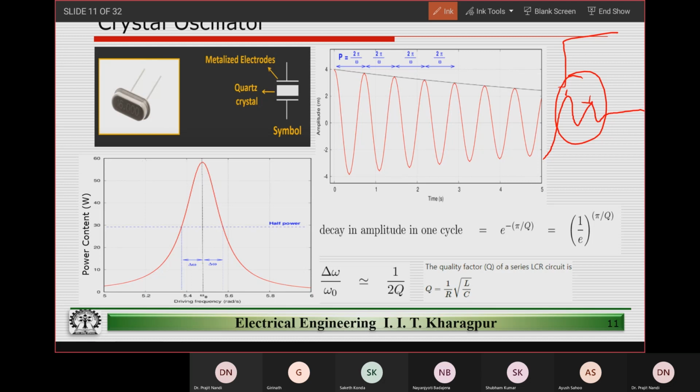Of course, I do the AC analysis finally, because when you are designing the circuit, you have to look at a lot of variations. But to start with, even the transient response gives a good understanding of how stable the system is. So if you have more peaks, the system is less stable, so lesser Q. Typically, if the number of peaks is, let's say, 4 or 5, then we say the Q factor is 5.